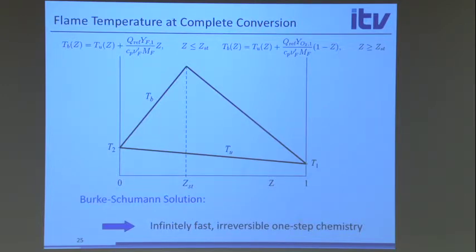So that, again, is interesting because now, if we locally know the mixture fraction in a diffusion flame, then using this flame sheet model, we can determine temperature and all mass fractions that appear in this one-step global reaction. We can determine these quantitatively. Okay? So you could think of this as the simplest combustion model, where you solve an equation for mixture fraction, and then locally you evaluate temperature and mass fractions from this model. Okay.